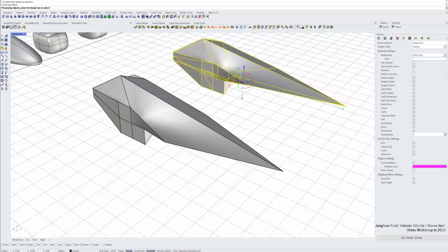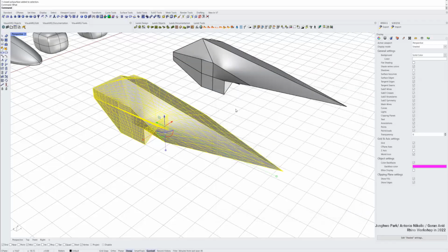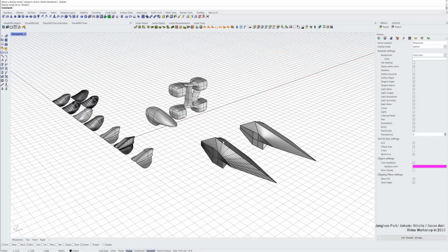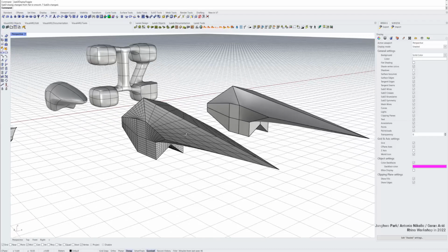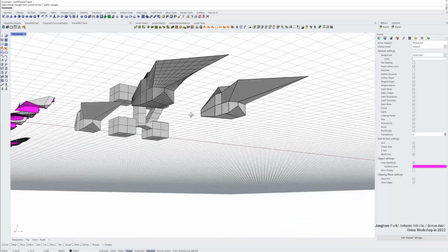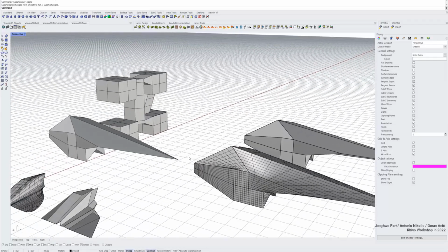one of them has to be NURB. So when I type what, this is SubD, this is NURB. So you can show the isocurve, but this is NURB surface. So that's another technique. You can add crease for the entire geometry. Then basically you get this kind of simplified model, and you can convert to NURB to play with it.